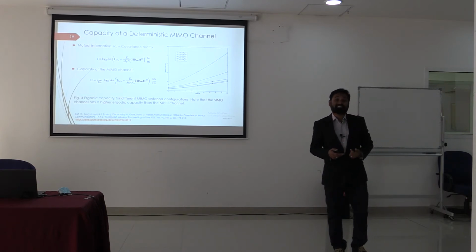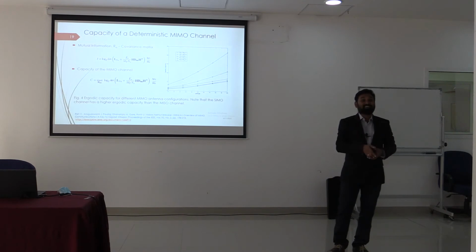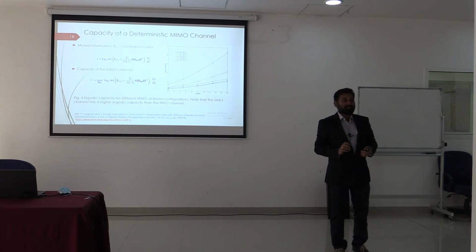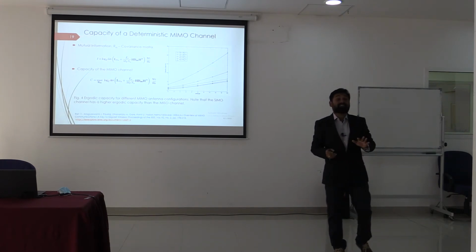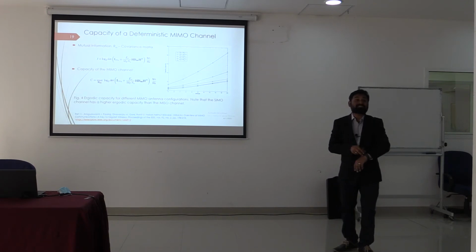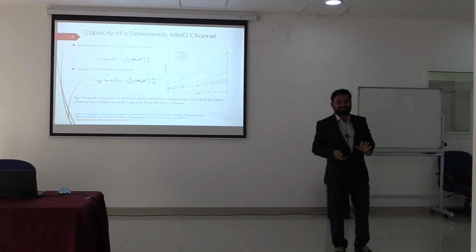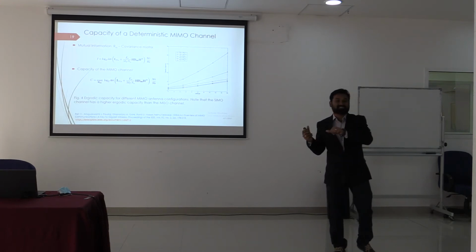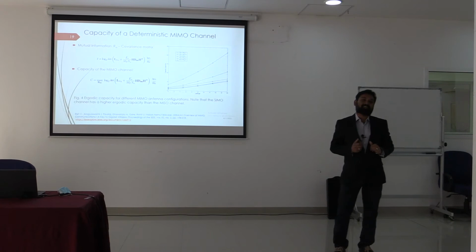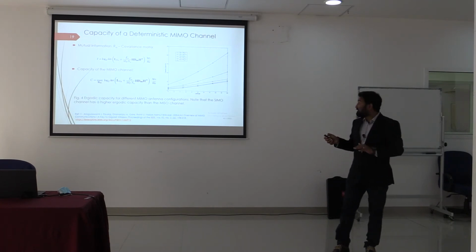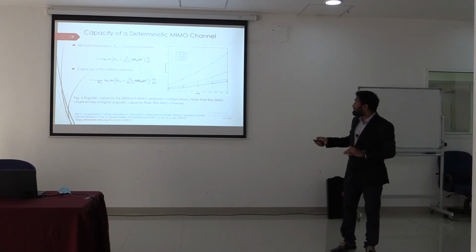Which noise is like that? If you take the autocorrelation function, it looks like an impulse response, a bell-shaped curve. No such frequencies or no such channel models exist from 700 megahertz to 7.125 gigahertz. You can model it as a thermal noise. So if you consider your channel is a thermally affected channel, you can use this Gaussian noise or additive white Gaussian noise channel model. It is not applicable for all the spectrum. So this particular paper has its own limitation.